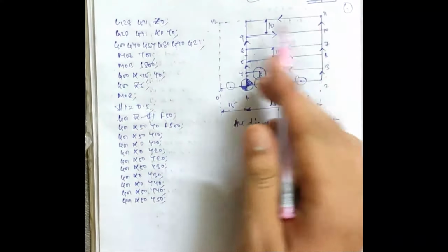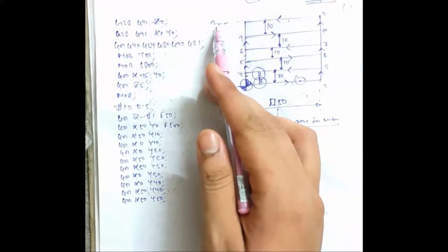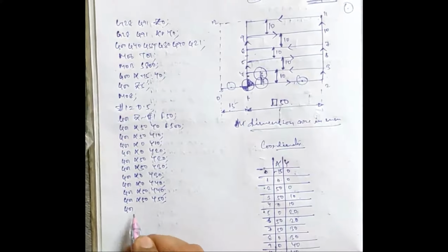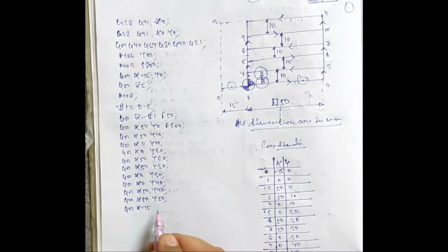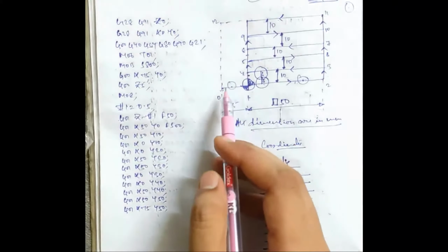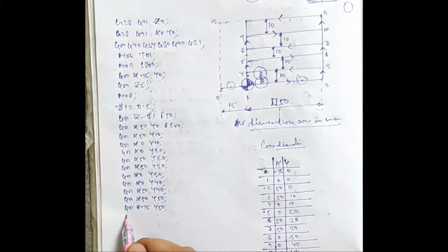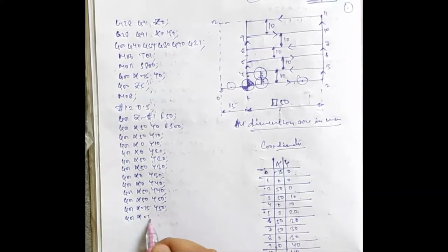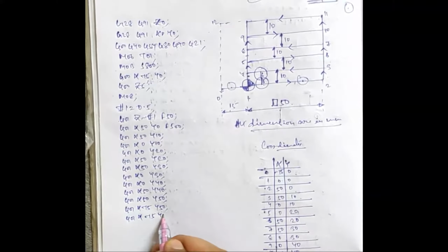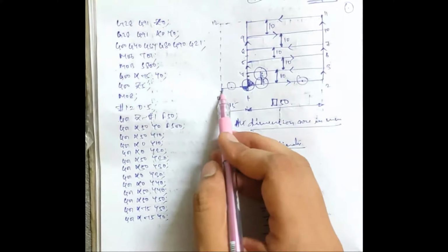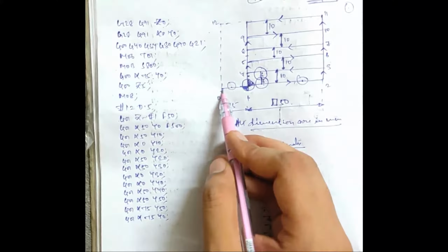Then 11 to 12 is a straight line and directly comes to point number 12, which is G01, x minus 15, y50. Then come to point number 0, G01, x minus 15, y0. So in milling, always complete the circuit. You start from 0, you have to end at 0.